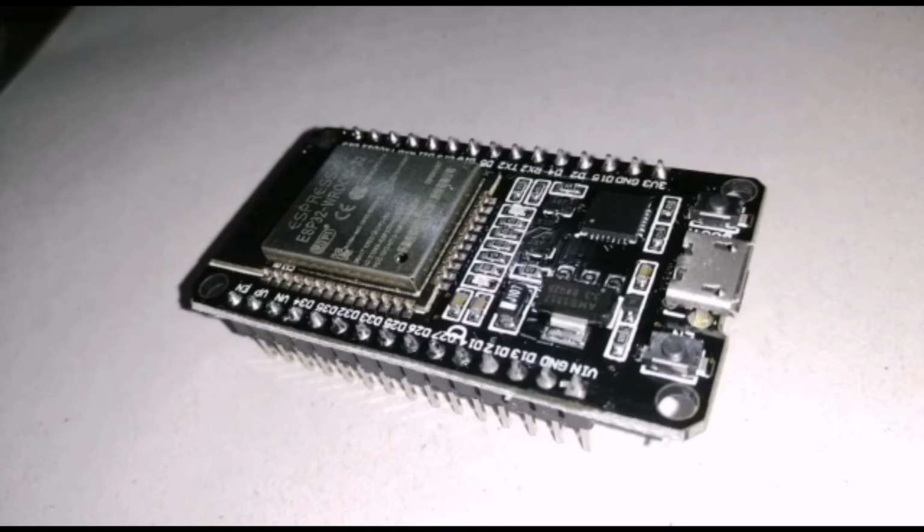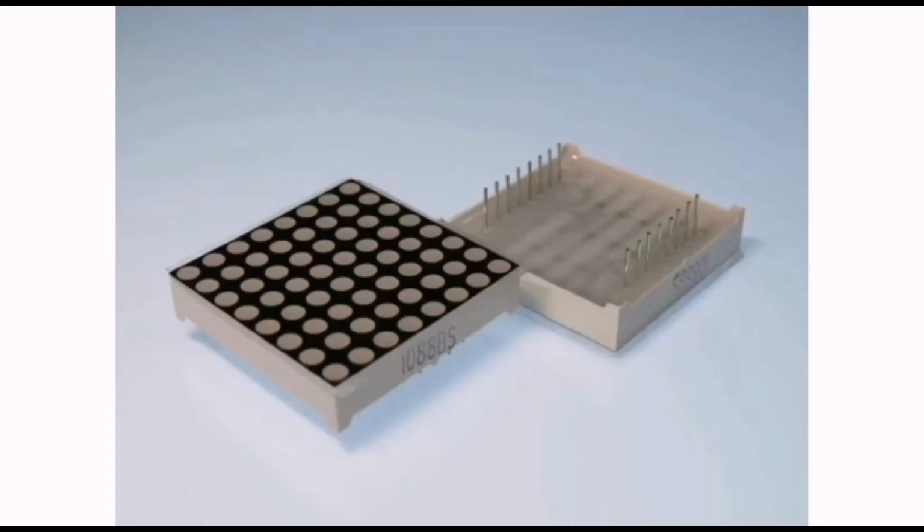It consists of 26 GPIO pins, out of which 16 pins are connected to the LED array. The microprocessor can be controlled using a DC power source. Therefore, a 3.7 volt Li-ion rechargeable battery is used. It's compact in size and weighs less than 50 grams, making it light and easy to incorporate on the rotating mechanism. Next we are coming to the LED array.